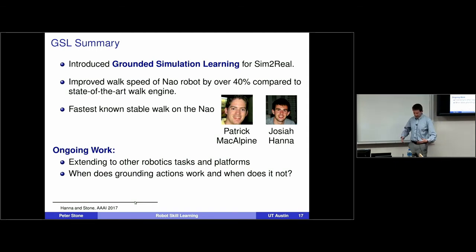Basically, we have a parameterized walk, which is basically varying the center of gravity and the stride length. It uses a double inverted pendulum model, so it swings the center of mass over the foot as a fulcrum of a pendulum, changes to a double support phase, then does the same. That opens up a whole bunch of parameters: how much should the body sway, the center of mass move back and forth, how fast should it go, what should the stride length be. Those are the parameters that are being optimized in the simulation part of this loop.